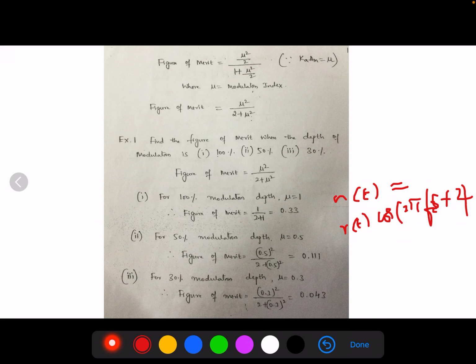By threshold, we mean a value of the carrier to noise ratio below which the noise performance of a detector deteriorates much more rapidly than proportionately to the carrier to noise ratio. So it is very important to recognize that every nonlinear detector, for example an envelope detector, exhibits a threshold effect. On the other hand, such an effect does not arise in a coherent detector.